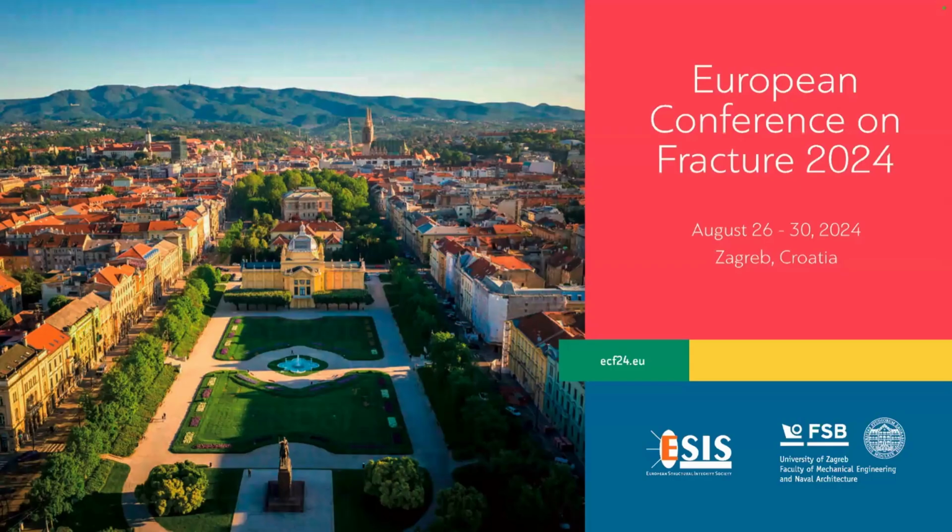Yeah, good question. Look, basically, if you talk about a pressure vessel, these cracks grow very fast. It's almost like an explosion. When I calculate the number of cycles, it's something like 0.1 cycles, so it grows immediately. In cases like this, the initial shape is not so important. But usually we use penny shape.